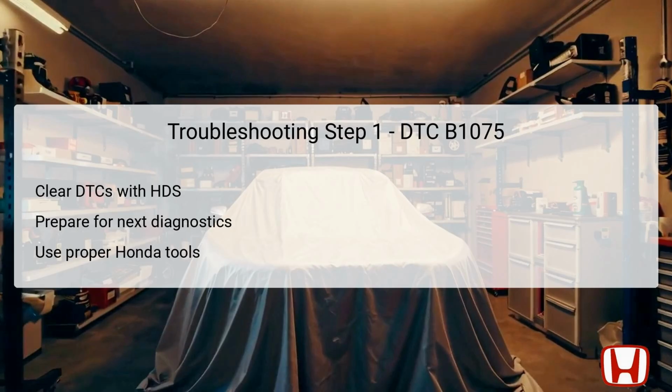Using HDS ensures that you are employing the proper tools designed for Honda vehicles, which can provide vital data and functions necessary for effective troubleshooting. After clearing the codes, you should prepare for the next steps, as this lays the groundwork for identifying if the issue persists or if the system's behavior changes. This step emphasizes the importance of proper equipment in accurately diagnosing Honda-specific issues.